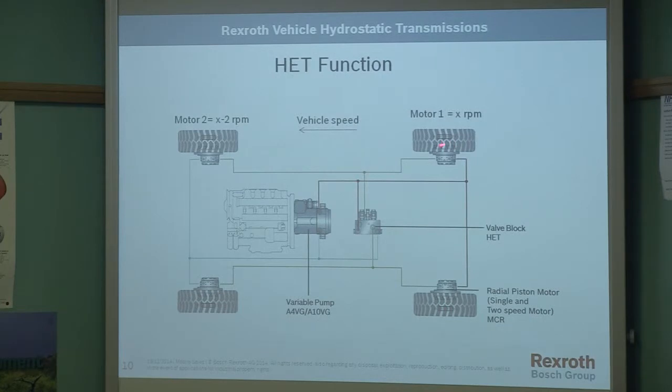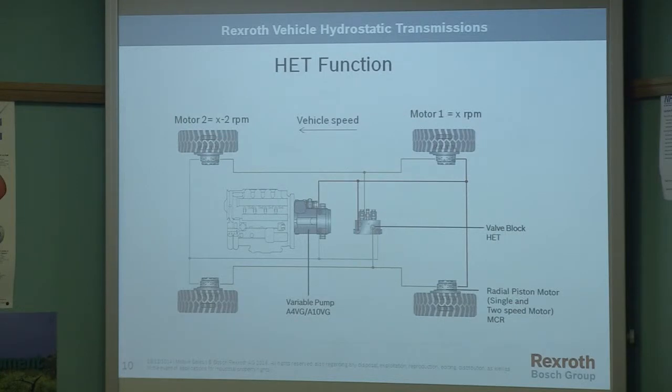So this motor is putting out a little more flow than needed, more than the leakage, because these are radial piston motors, leakage is quite low, but we're bleeding off a little bit of flow here. What that means is this motor doesn't get sufficient flow to create much traction. It's normally 90-10 because we're bleeding flow off. So these motors are almost freewheeling. They're being driven by the ground effectively.